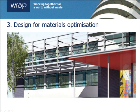The third principle, design for materials optimization, aims to reduce waste streams on-site. There are three main areas in which waste reductions and cost savings can be made. Firstly, excavations should be minimized so that material does not have to be distributed elsewhere on-site or removed altogether. Secondly, the standardization and simplification of materials, sizes and components will lead to a reduction in the different types of materials on-site and a corresponding reduction in the number of waste streams generated. Thirdly, dimensional coordination can deliver waste savings by minimizing offcuts.